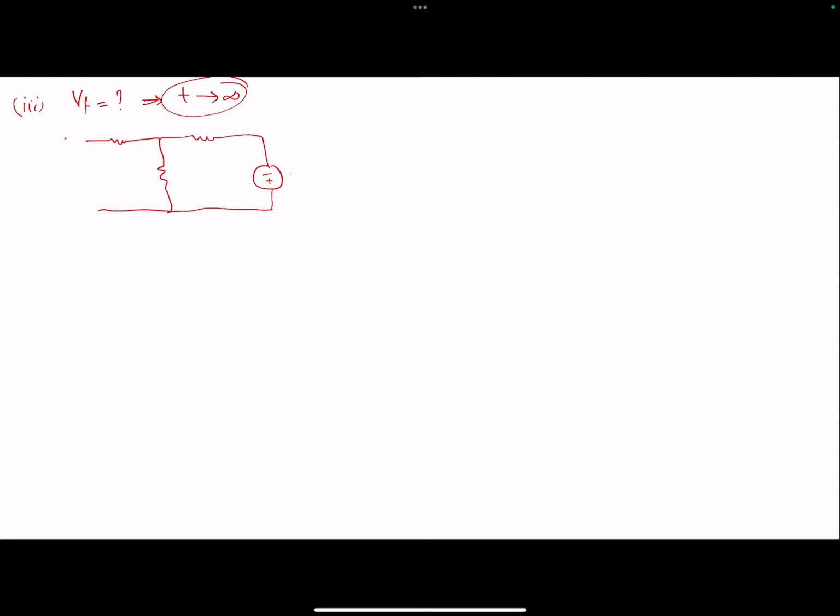So this is 75 volts, and then you have 40K, 160K, 80K, 40K, 160K, and 8K. And this is the capacitor final voltage value. Again, this is when time approaches infinity because a new steady state has been reached. Of course, this is going to be reached way before infinity, by the way, because we know that after 5 time constants, things are pretty much at the steady state.